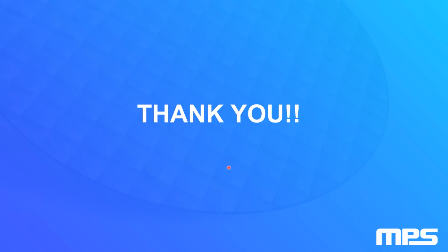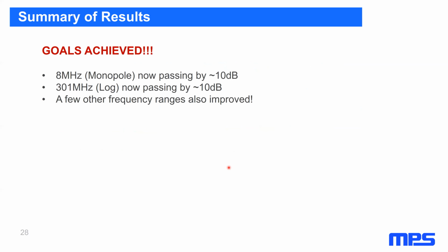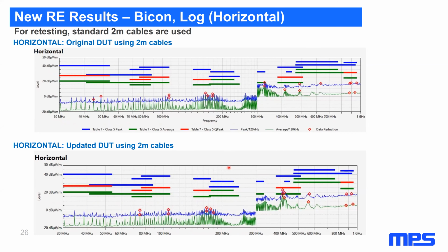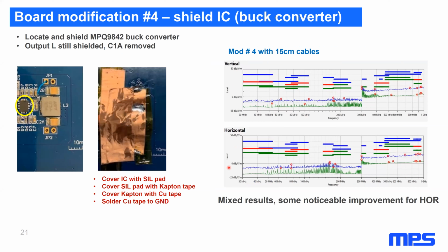But this one more complex one was, when adding the copper tape shields to cover various areas on your DC-DC converter circuit, the shield will also add parasitic C to the ground that will be determined by the insulator you add, for example, Kapton, Sil-Pad, etc., and its thickness. I'm not being critical of this method, just wondering if you've ever tried different spacings away from the component of interest, and if so, did it tend to make a significant difference?